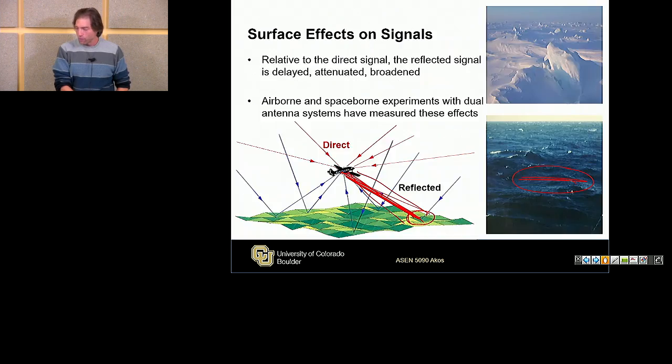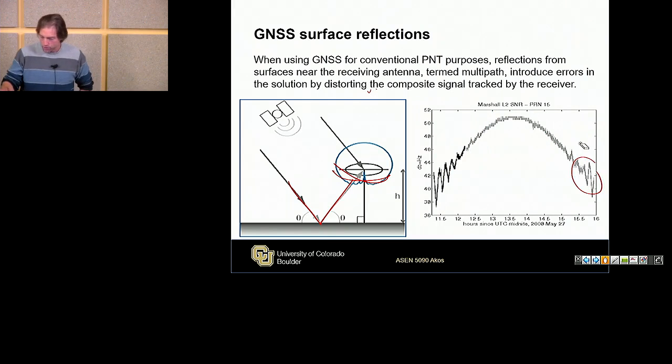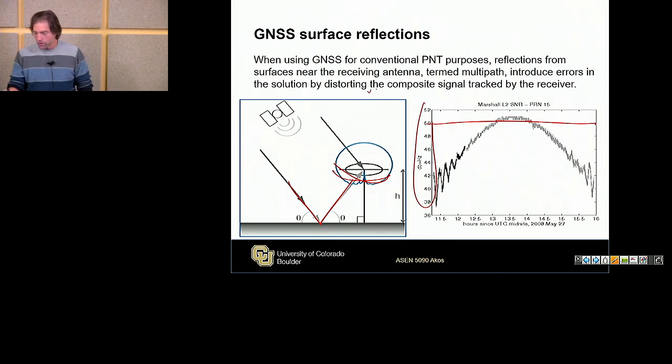If I jump back, okay, this is just kind of a fun question. If that truly is the case, and I erase this piece here, and I look at my CN0 as a function of a satellite elevation pass, how come it's not flat all the way across the pass? Trick question. Do you guys know? Guesses?